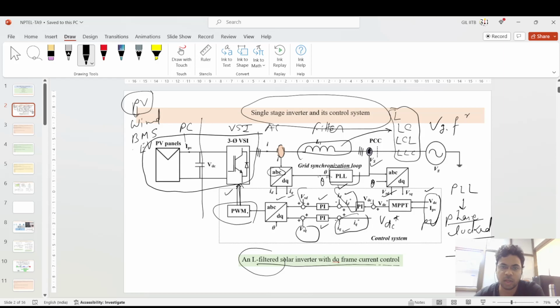The basic crux of this circuit is that you have to convert from DC, generated from the PV side, to AC using a synchronized voltage, because on the AC side you have AC voltages VA, VB and VC, which are 120-degree phase shifted, with a constant omega t.